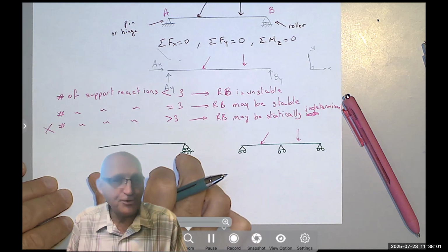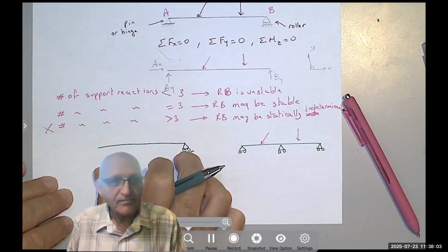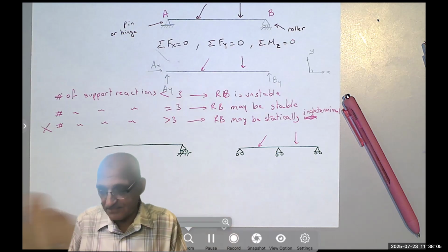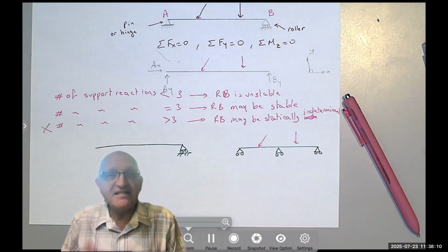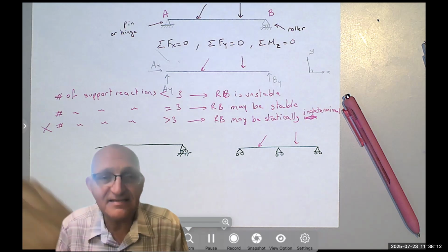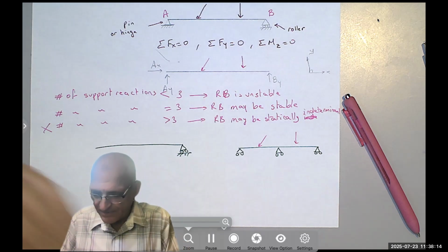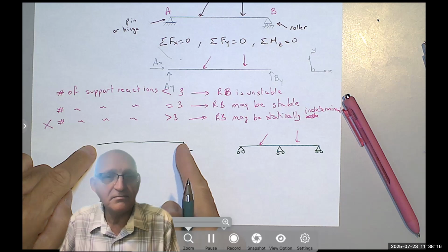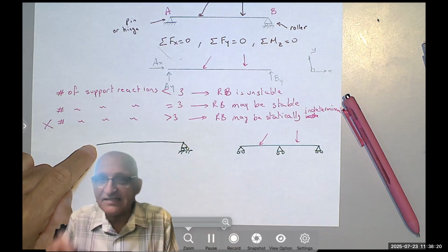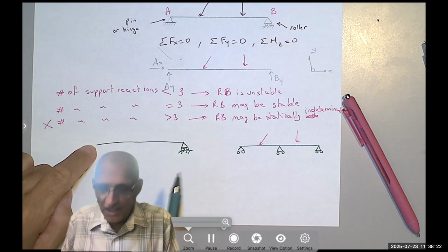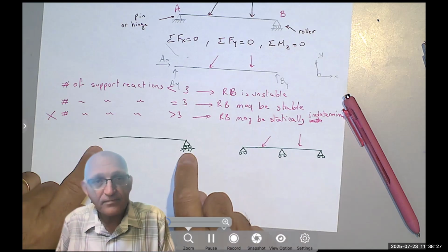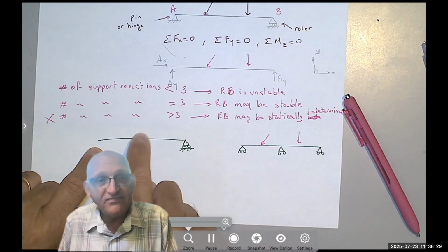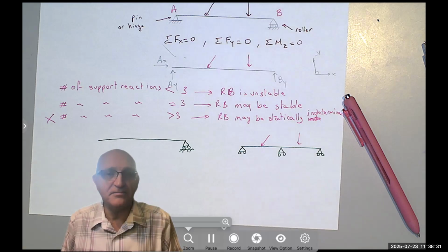Suppose this was a bridge or some other steel beam, and then you come to a day that is extremely hot. What happens to the length of the beam? This beam will get slightly elongated, right? So if those two were hinges, that will develop stress inside the beam.